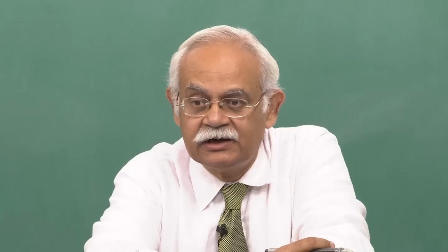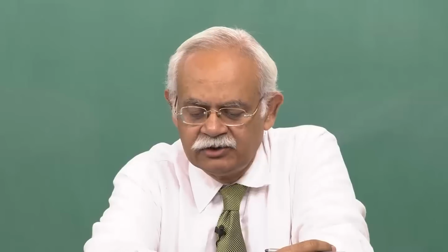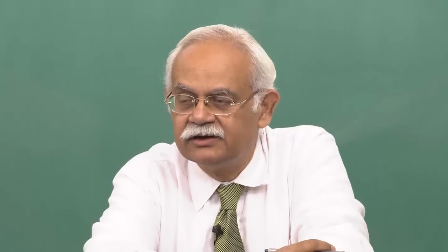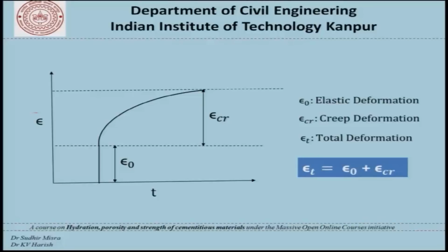Now once we talk in terms of sustained load and so on, we obviously have to talk about the increased strains under sustained loading. So now we talk of a strain over time. There is what is called elastic deformation, then there is something called creep deformation, and this is the total deformation. So this creep basically is the phenomenon that is increased deformations under a sustained load.